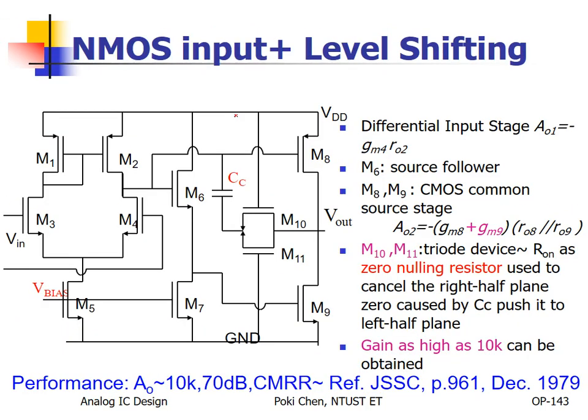And then, how about this structure? The same. But for the feedback, we have not only a capacitor, but this one. This is what? The so-called transmission gate. But it is turned on, right? The NMOS is connected to VDD, the PMOS is connected as well, so both are on. For what? To emulate a resistor.